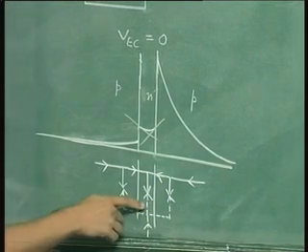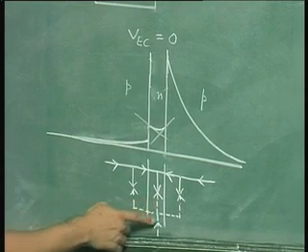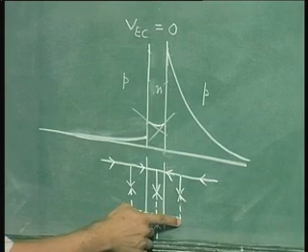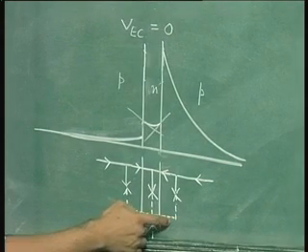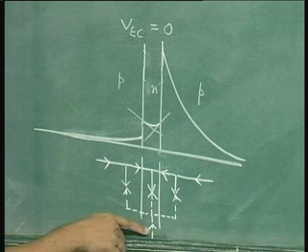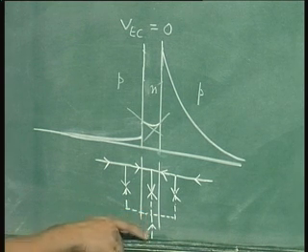Please note that the arrows indicate the direction of flow of the particular carrier, and the dotted line is electrons. So if electrons are flowing in this direction, the conventional current because of electrons would be in the opposite direction. This is to be understood. So the base current is outward, okay, conventional current is outward, electron current is inward.